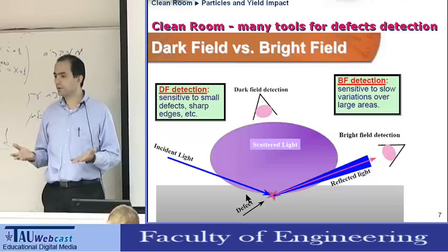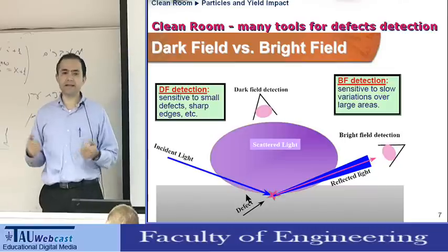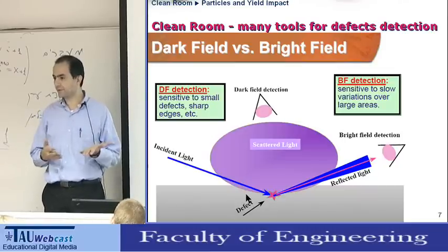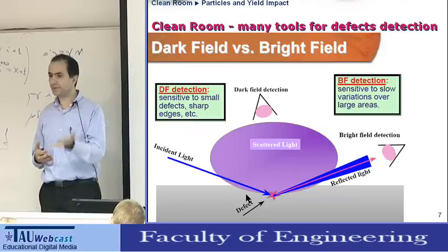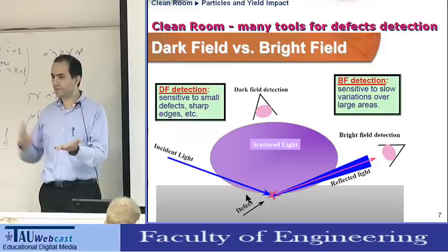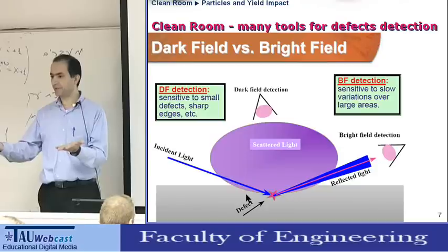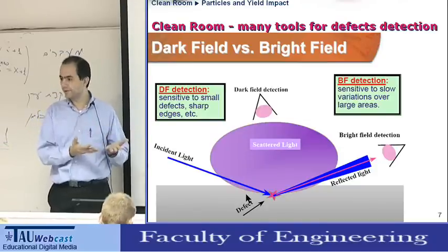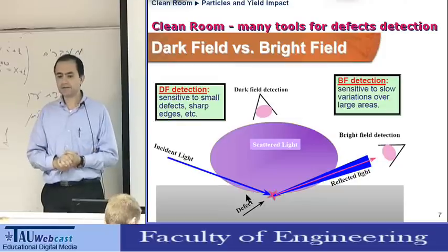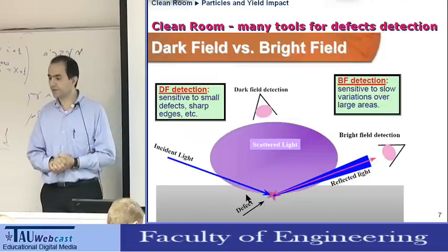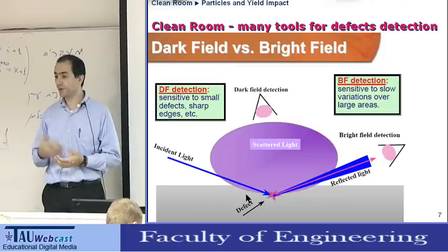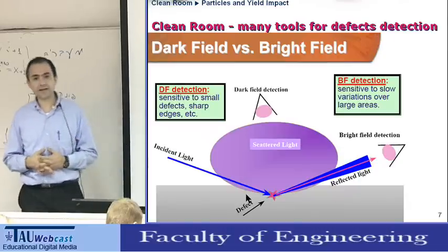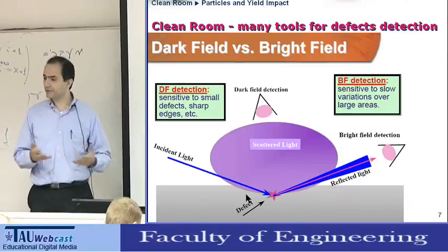If the tool that is being used, for example, an etch tool, has 2 chambers, it's enough to check the first 2 wafers, because one reflects the particles from one chamber and the other the particles from the other chamber. So if suddenly one chamber goes bad, it's enough to measure 2 wafers in order to check that. So it depends on the capacity of the inspection tools, the cost of the inspection tools, and so on. We try to get the maximum detection for the cheapest price.